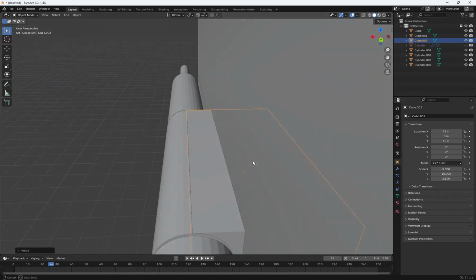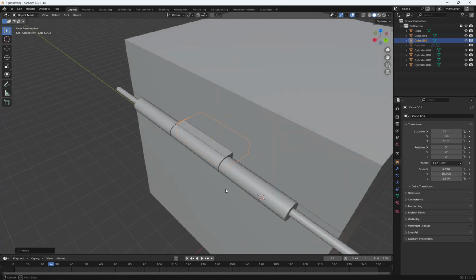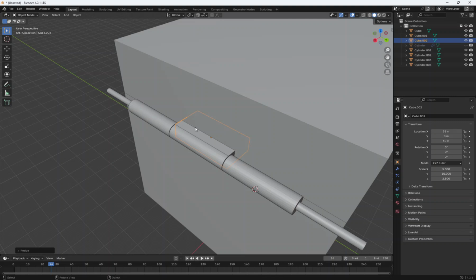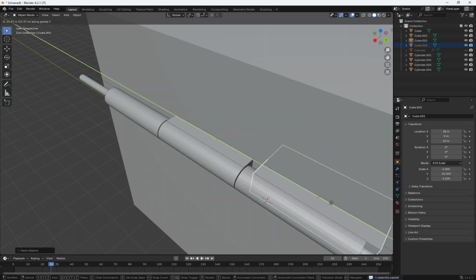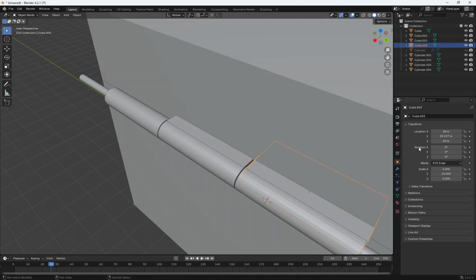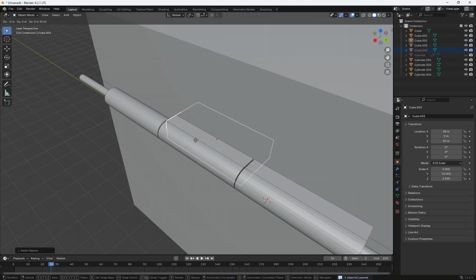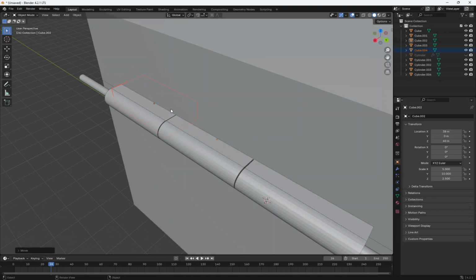All right. So now we've got a cube, and I'll show you how we're going to use that here in just a second. But first I want to copy that and paste them on the other two spots too. So Control-C, Control-V, G to move it in the y-axis. And get it kind of close, select it again, and we want to make that 20.2. And then we'll select this one again, Control-C, Control-V, G for move in the y-axis, get it pretty close, which I'm not. There we go. Select it again, and then that's negative 20.2.